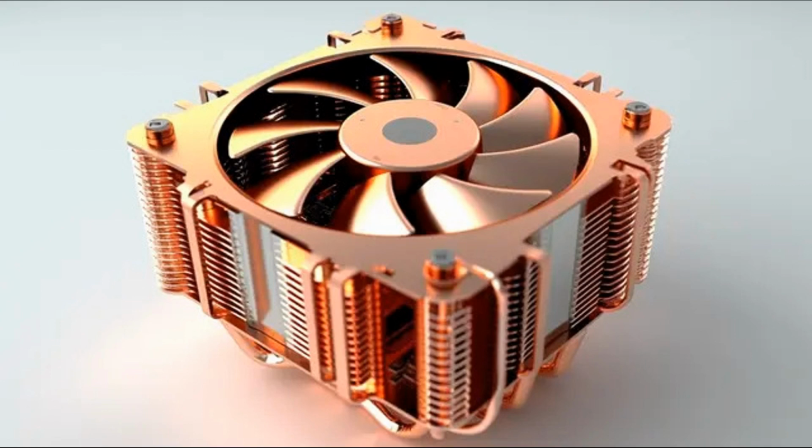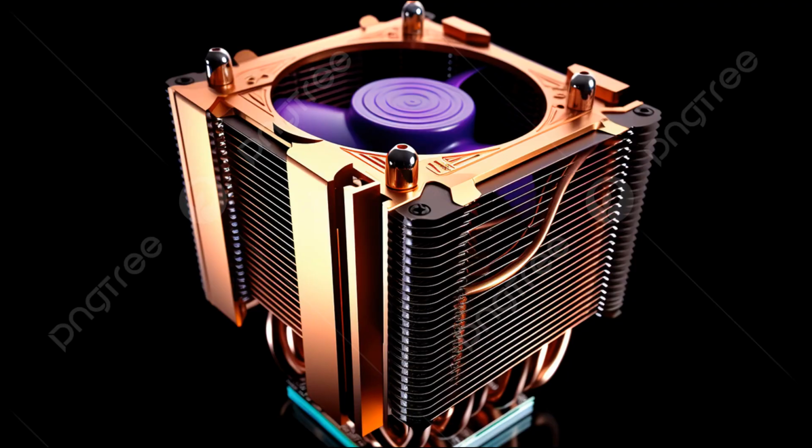High thermal conductivity. Heat pipes have exceptionally high thermal conductivity, allowing for efficient heat transfer over long distances with minimal thermal resistance. Uniform heat distribution. Heat pipes facilitate uniform heat distribution across the surface of the heatsink, ensuring effective cooling of the entire component. Directional flexibility. Heat pipes can be bent or shaped to accommodate different orientations and configurations, making them adaptable to various cooling requirements and space constraints. Passive operation. Heat pipe heat sinks operate passively, without the need for additional power sources or moving parts, resulting in silent and reliable cooling solutions.